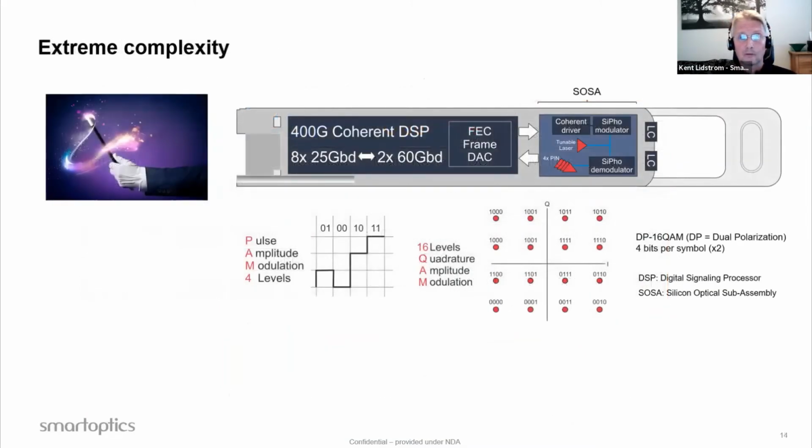If we try to very quickly, on a high level, follow what those are doing: in the small form factor here, they have 8 electrical lines coming in on the back of the transceiver. Each lane uses 25 gigabaud or 50 gigabit. So that's how they form the 400 gig.